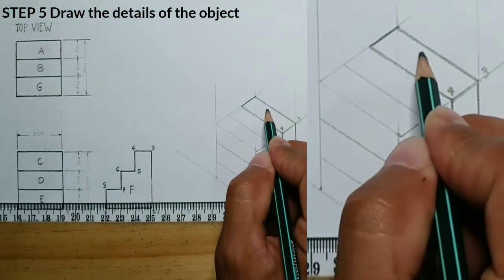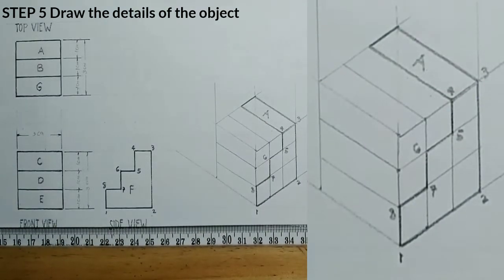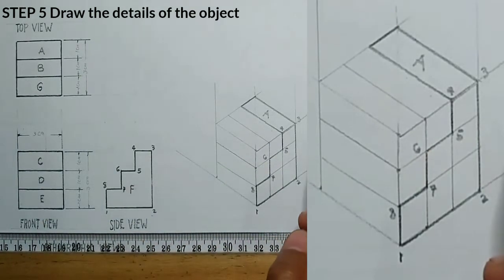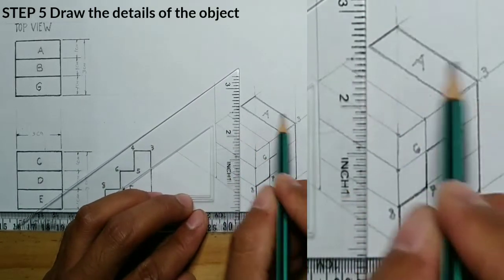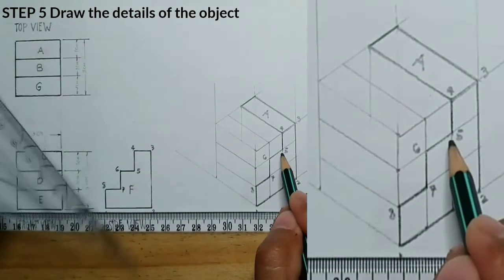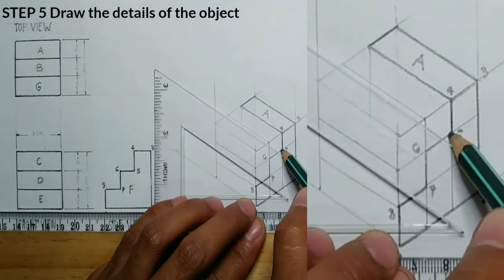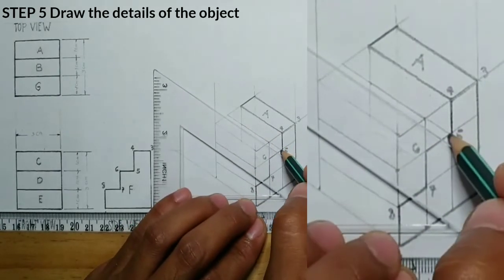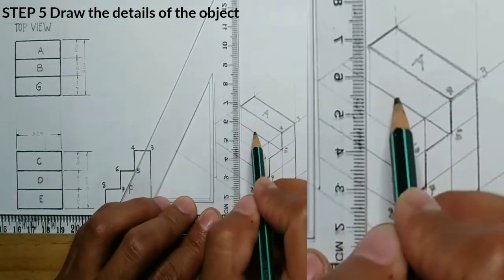So this is surface letter A. Next is surface letter C from the front view. So this is how to do. From this corner, you project a line downward, and from this point, you project 30 degrees left. So these are the details of surface letter C.